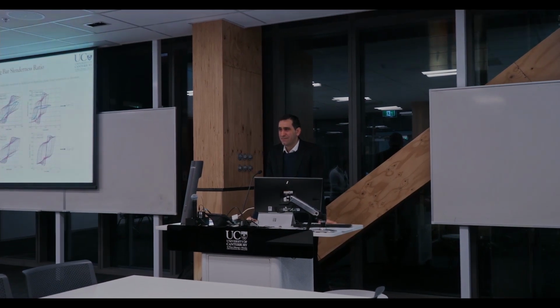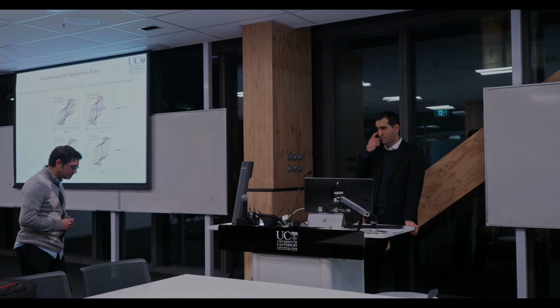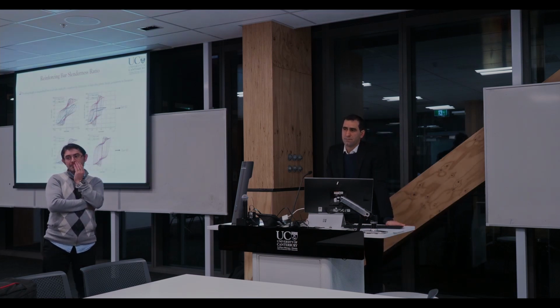Okay, I think it's fine, we can wrap up. But as you are working in that field, one good thing to remember is that currently the design codes only look at anti-buckling as well as confinement properties similarly, right? Whereas research has shown that confinement, which is the ability of the core concrete to withstand large strain, depends on the amount of stirrups, whereas the anti-buckling performance depends on the arrangement of stirrups. And that is the factor which is missing in all codes, be it ASCE, New Zealand or Japan. Now, the instructions to get the calibration parameters for these plastic hinge models are based on ASCE 41-13, that table which looks at well detailed, not well detailed, shear to flexure ratio and all those things, right?